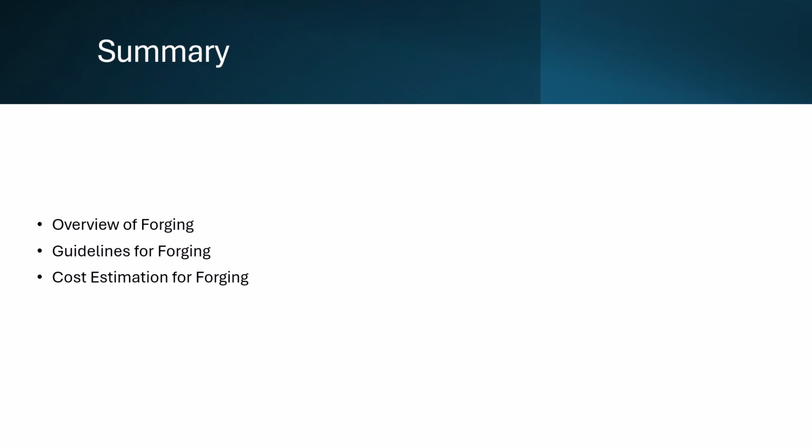To revisit what we've talked about today, forging is a manufacturing method that involves deforming, not melting, metal into desired part geometries. This method leads to good toughness and strength, but does create a lot of wasted material via flash and webs. Multiple dies may be needed to complete the necessary preforming. There is a wide selection of machines to select from to perform the process, but a narrower selection of materials that are able to be worked without cracking.